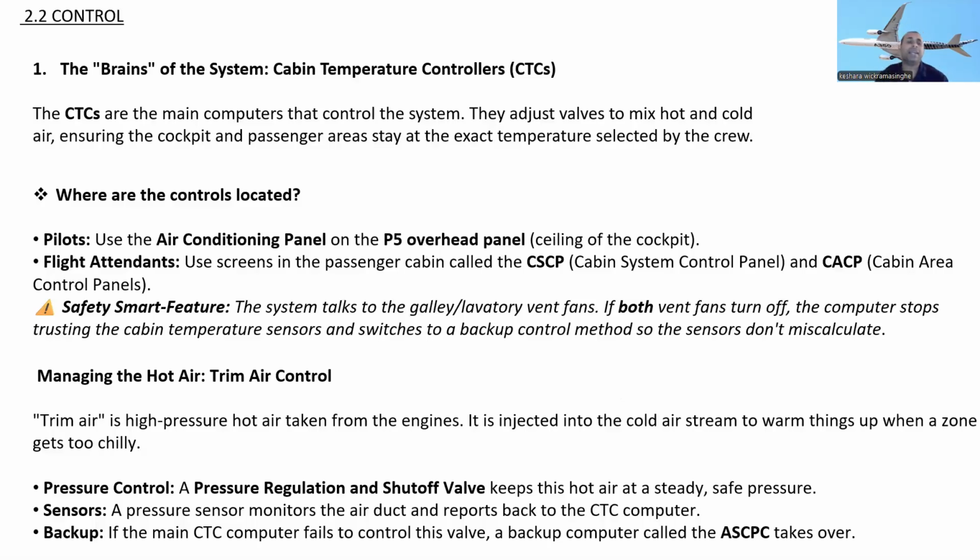All right. So managing the hot air: trim air controls. Trim air is the high pressure hot air taken from the engine, and it is injected into the cold air stream to warm things up when a zone gets too chilly. If it is too cool, they take the trim air, mix it with the air, and distribute it.